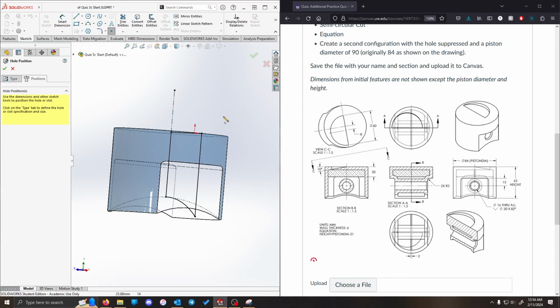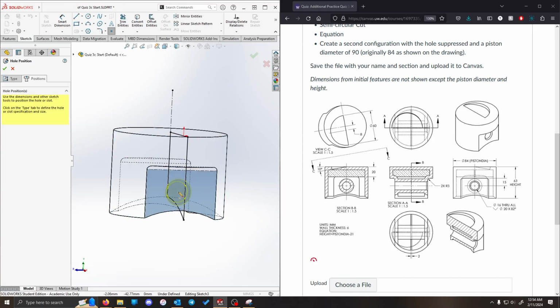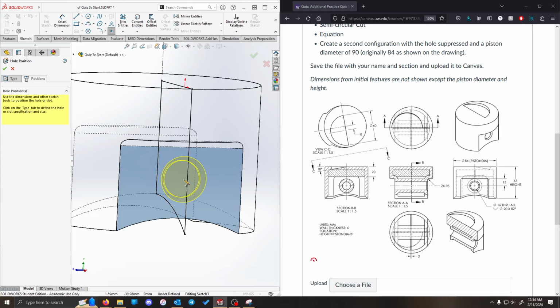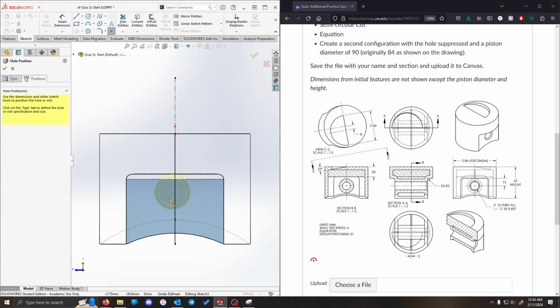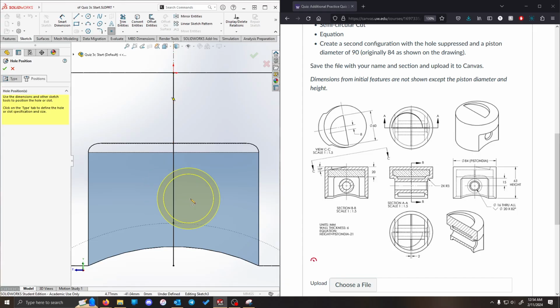I'm going to open the position tab, and because we had that surface selected, it's going to auto open a sketch on that face. I'm going to press Control 8 so we can see things a little better. And we want it right in the middle. So I'll just place mine off to the side so we can go about defining it manually. Hit Escape to deselect our tool.